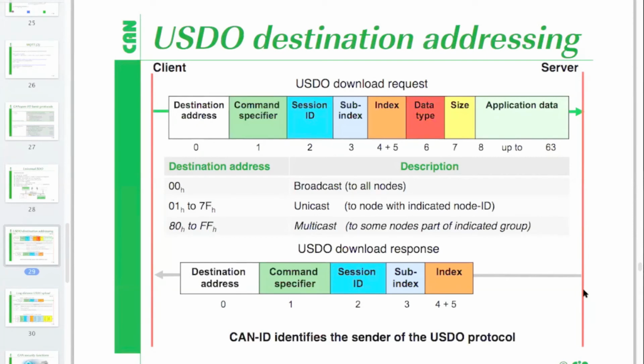This is the new structure of such a message, which on the CANopen embedded level is responsible for collecting or writing the data into the gateway, the process data, which will later go to the end user over the cloud services, condition monitoring, whatever IoT-based stuff it is. So we actually configure all the data in the large message, which has 64 bytes. We have this possibility now.